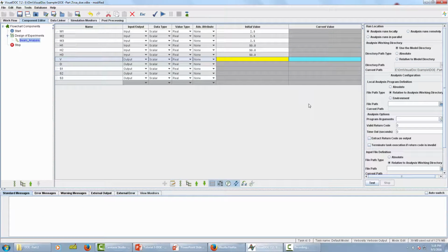When coupling analysis with optimization, it is necessary to have an input data file and an output data file that correspond to the analysis program. The input data is utilized to override values that correspond to the design variables. The output data is utilized to extract output responses. During optimization, the input file is modified by VisualDOC automatically and the output file by the analysis program.